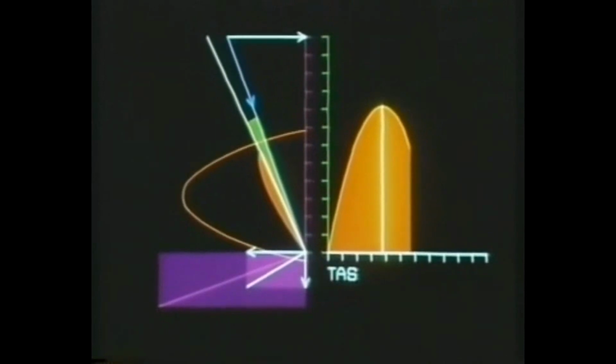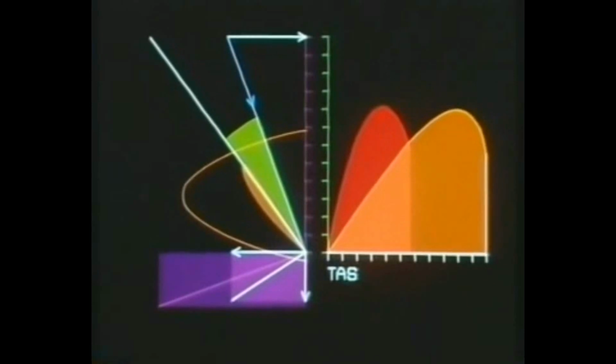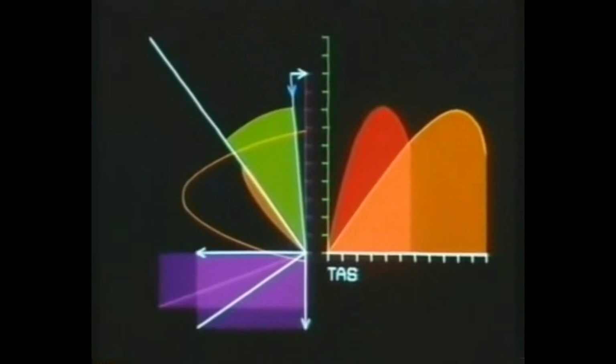This propeller is a fine-pitch propeller, giving good performance for takeoff and climbing, but a relatively low maximum speed. By increasing or coarsening the pitch, the maximum speed can be increased, but there are practical limits to the size of the blade angle that can be used, since too large an angle might mean the propeller could be stalled when the aircraft is stationary or moving at low speeds. Torque would be high, so RPM would be low, and because the direction of the total reaction is further from the direction of flight, less thrust would be produced, and acceleration would be too slow for takeoff from normal airfields.